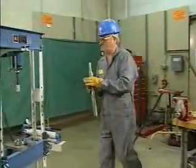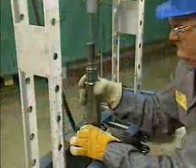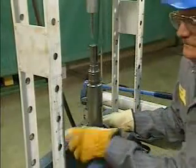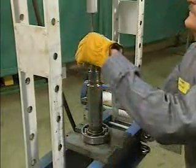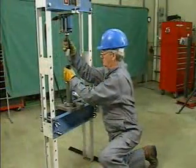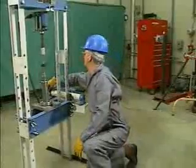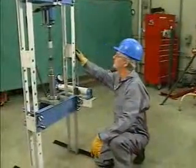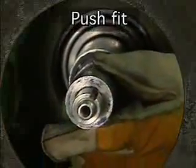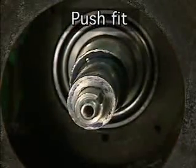Bearings are precision parts, and they must be installed as precisely as possible. How the bearing fits onto a shaft and the kind of mounting that is used are both important to the proper functioning of a bearing. The term fit refers to the tightness or looseness with which a bearing is installed onto a shaft. There are two kinds of fit: push fit and press fit. A push fit is a fairly loose fit. Usually a ring that has a push fit can be pushed into place by hand.